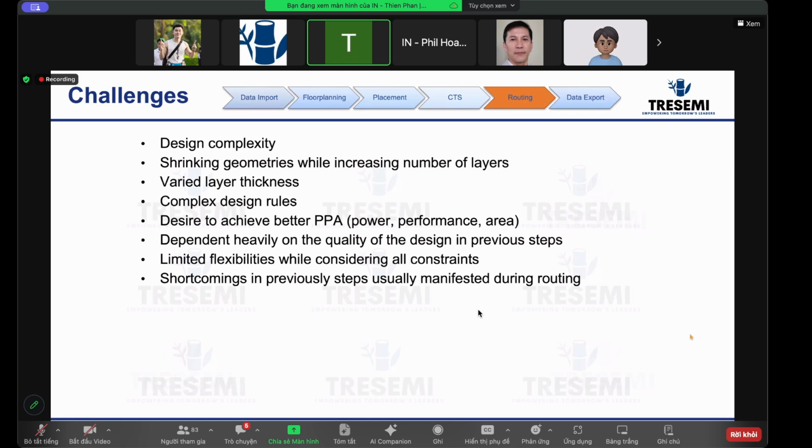The global router plans out everything, but when the detailed router comes, not all of that planning will be used. If there's no congestion, more likely a high percentage of the global route will turn into real route.